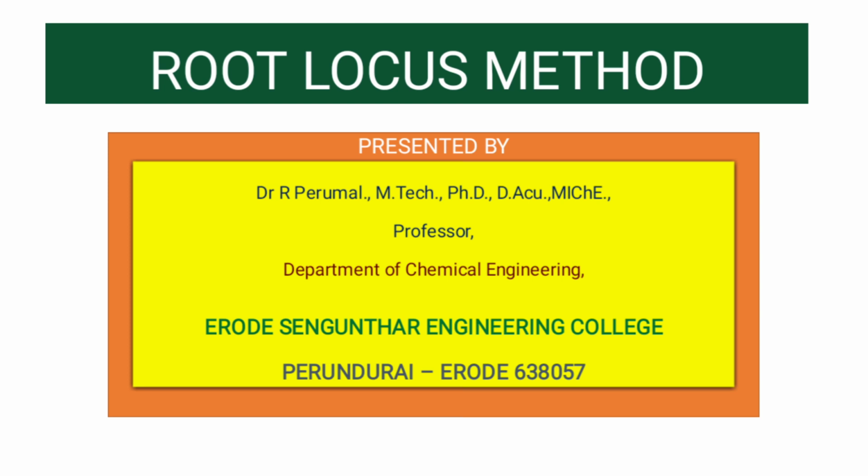If any one of the roots lies on the right half or on the axis, the system is said to be unstable. So if we want to say a control system is stable, all the roots must have negative real parts.